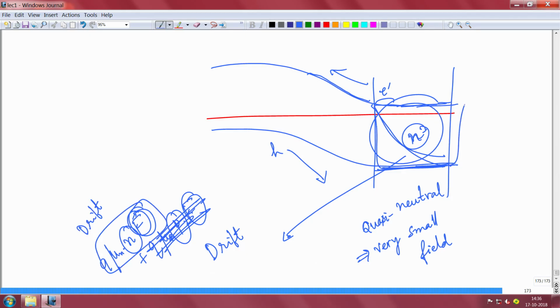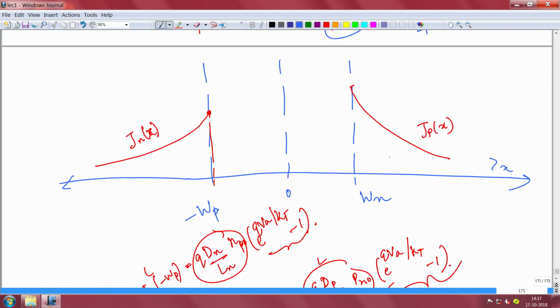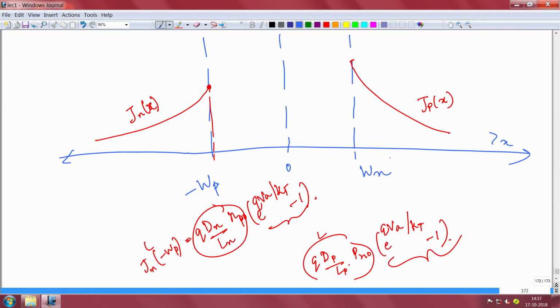because of electron in this region is not negligible. Similarly, the drift current of holes in this region is not negligible, okay, drift current is not negligible. So, those drift current components, and there could be other components also, like majority might also diffuse in small quantity, right. So, all those components will basically make sure that the total current here has to be constant. I will call it J because it is the current density, I am not taking the area, J total.